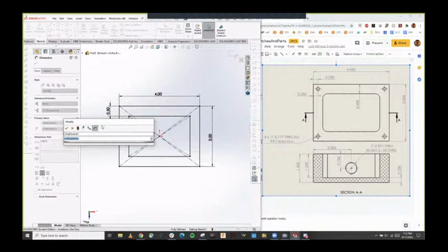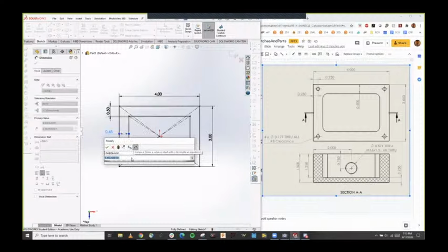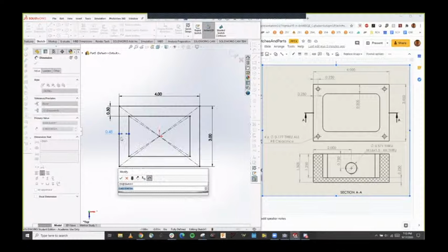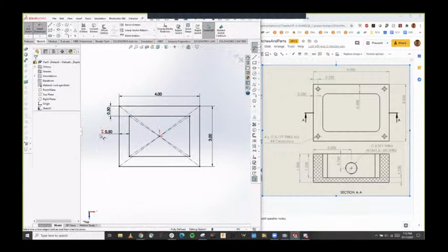Now, one thing we can do as well, which is an extra tidbit, is use something called equations. In this case, we want the thickness to be uniform around all sides, right? So we can hit the equal button, which will create an equation, and I can click on this dimension, and now those 2 dimensions are equal. You see the red sigma denotes the equation. One step further, for anyone interested, is that when we get into the full model, there's something called global variables.